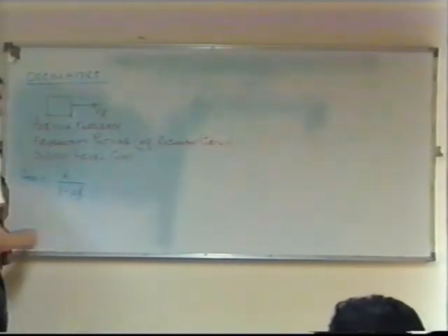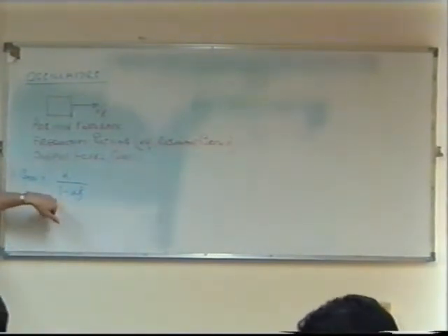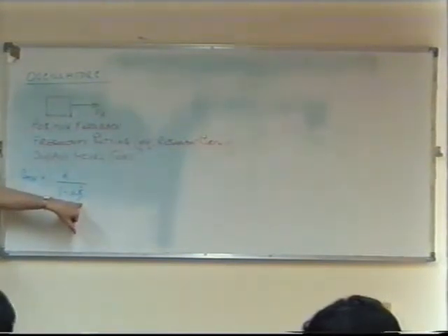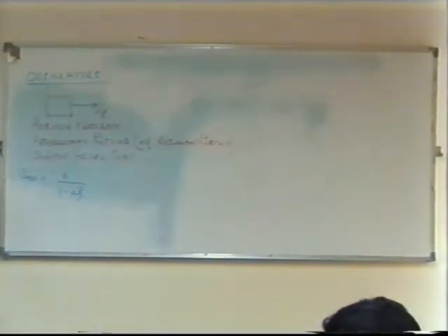That's right. Yes. Now, if you have a very high gain amplifier, then beta doesn't have to be very big before this becomes 1. And 1 minus 1, of course, is 0, which gives you an infinite gain, which is the condition for an oscillator. Anything bigger than that, and you overdrive the output. So you distort, in other words, your signal. So there has to be some sort of level control of the output. Again, we're not going into actual circuits, but this will be part of the oscillator. These are the three conditions for an oscillator to work.